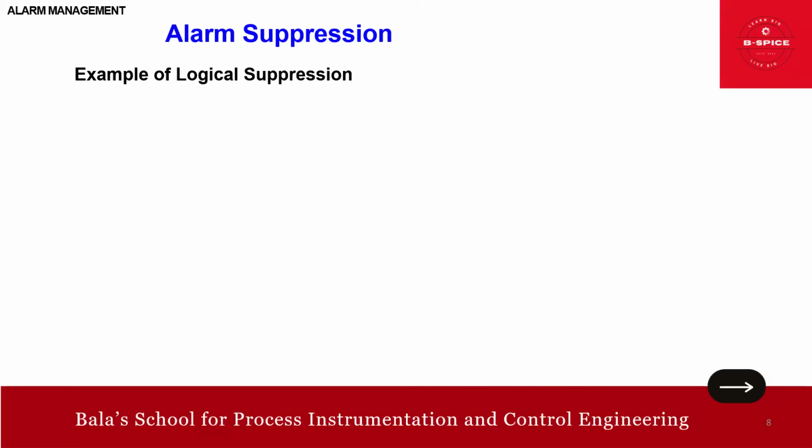Then with two machines, the second of which is automatically started upon loss of the first, your time delay is configured to allow time for the second machine to start, for example, 5 seconds before a fail to start alarm is initiated. This is very usual, right? We can do this. Okay, so that is one example.